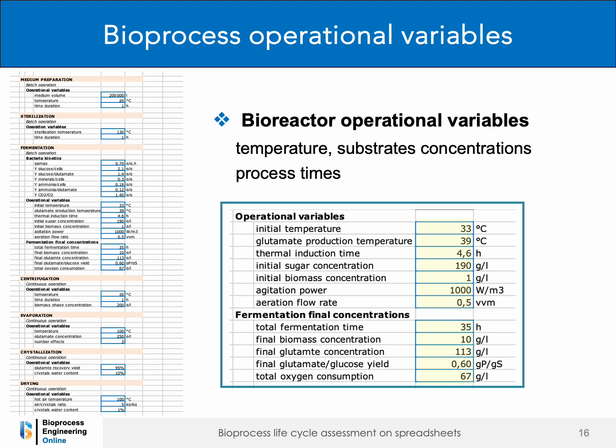Furthermore, the spreadsheet must specify or calculate the outcomes of biotransformation under fixed operational conditions. This includes determining the fermentation time necessary for sugar utilization and the resulting final concentrations of biomass and metabolite.